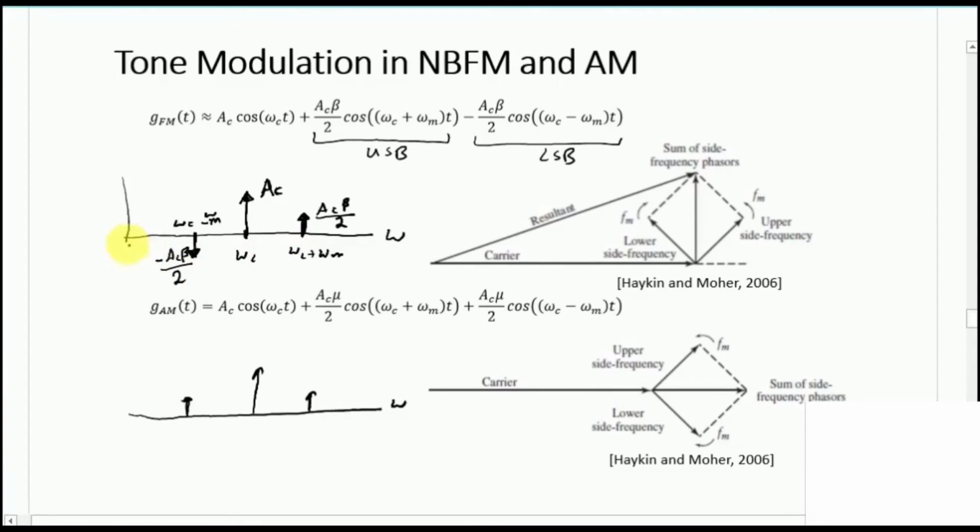So the bandwidth we have similar on the negative side. But the bandwidth is basically concerned with the positive frequencies. So the bandwidth over here is starting from the frequency omega c minus omega m, the lower sideband, to the upper sideband, and hence this is equivalent to 2 omega m.